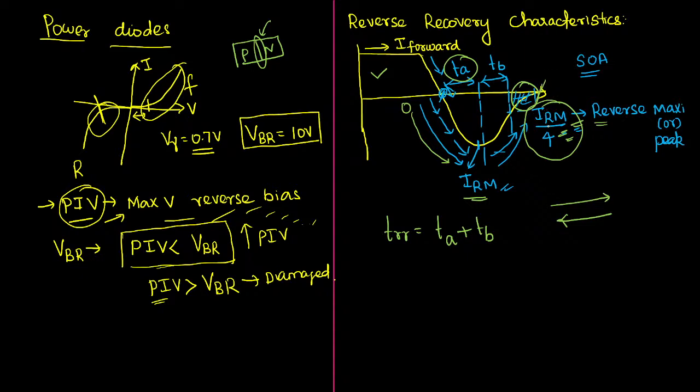I am not saying that we are waiting till the zero point of the maximum current. No, we should not wait. I told you practically that it will not happen. It will take a very long time, so we can't wait till that point. So we are considering only 25%. This time is simply defined as the reverse recovery time. I hope you all have understood this.